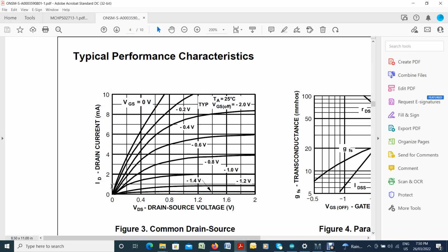And here these characteristic curves, drain current versus drain to source voltage, are almost straight lines. In fact, the smaller the drain to source voltage, the more straight these lines appear to be. So the drain to source resistance is the inverse of this slope. So it's delta V over delta ID. So as the gate to source voltage decreases, becomes more negative with respect to the source pin, the resistance of the JFET channel increases. And if you're getting out to here, you're operating nonlinear.